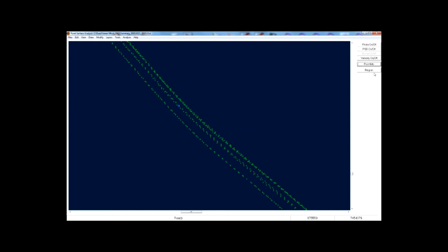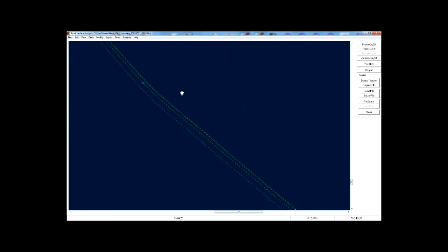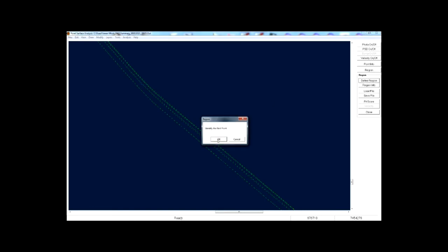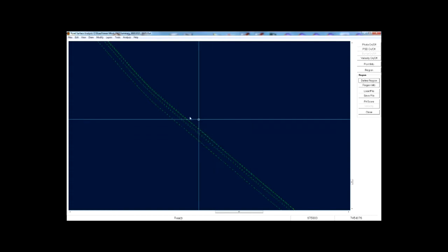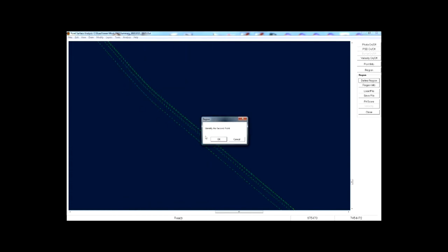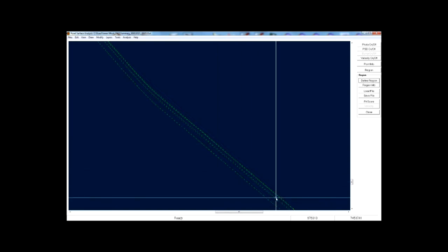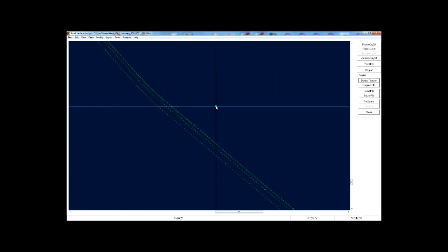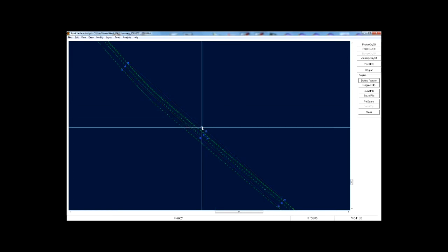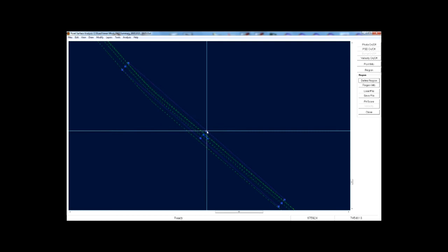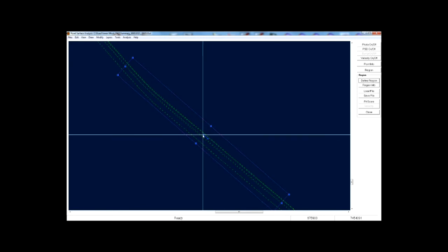We can also do a region, so we process a rectangular region we've defined. If we slightly zoom out, we define the region according to picking of 2 points. So we select Define Region, identify the first point, perhaps we'll pick that point, identify the second, this point. We get a rectangular display that's not covering all the points, so we can select it, and we have these grips where we can change its size. So we've now made it larger. We can also move it around and if necessary rotate it.